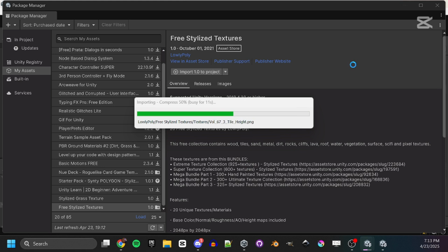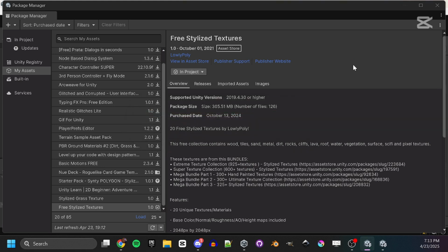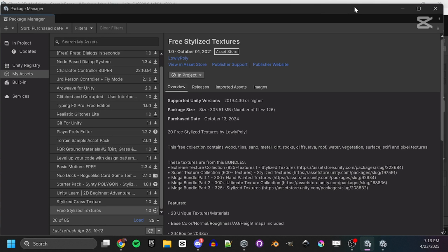Note that when you do this, you have downloaded that package onto your computer. And if you do this a lot, you'll wind up with tons of that stuff on your computer, and you actually have to go in and find it and delete it or remove it, not just from the Unity projects that you're using, but from Unity's download area. So, it will eventually start eating up quite a bit of space. Unreal is way worse about this kind of stuff.